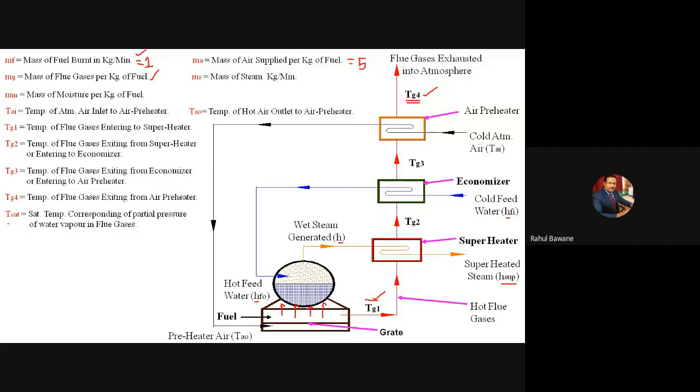Likewise, when your steam has 0% moisture, that means it has reached the saturation temperature of steam, or that is the vapor pressure. So T saturation. After T saturation, if you add heat, your steam starts superheating. Now 105 degrees centigrade steam, 110 degrees centigrade steam. So superheating will be there.